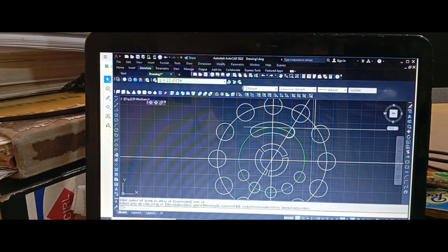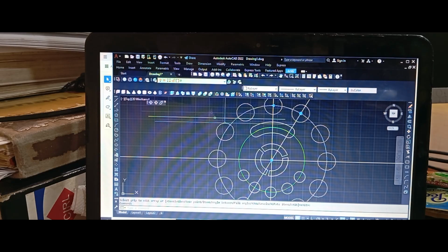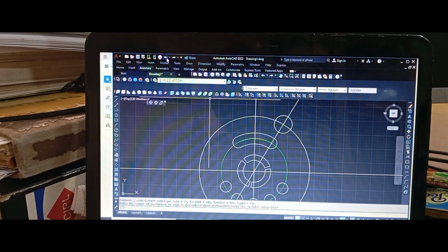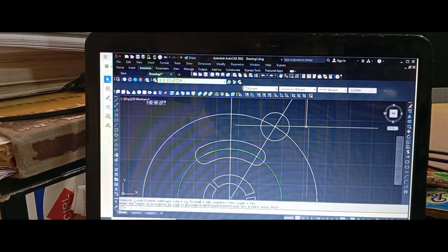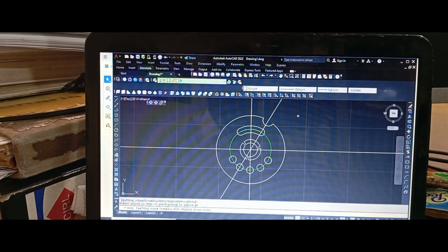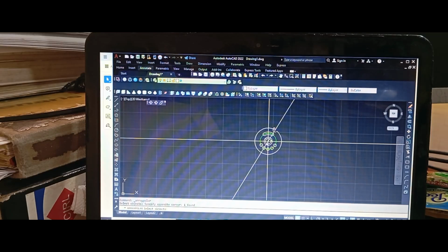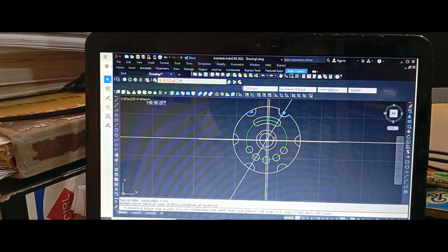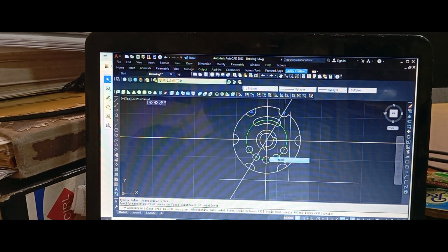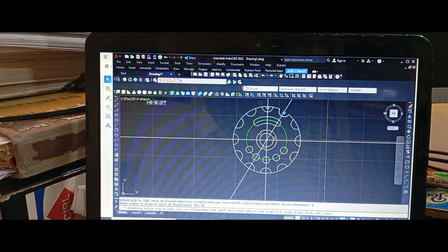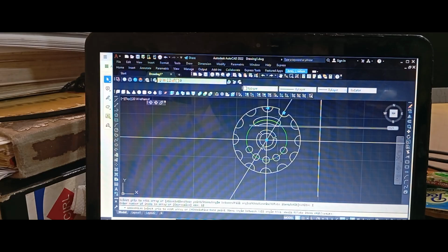The next thing to do, I may not even start with polar. I may not go polar now. Let me do some trimming from all the shapes, right? Good. So I will now go polar with that shape in place. Click the center line, right click, item 12. If that is in place, I can accept that.